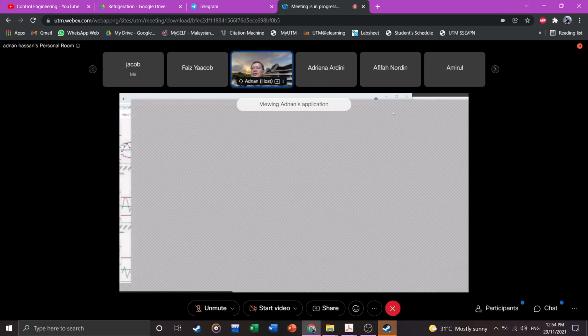Okay, 1 point above 3 sigma, that's one rule. Please put in the chat box the rules that you have learned today, the runs rules to identify an unstable process within plus minus 3. What are the other rules? Okay, 14 continuous downward or upward, good.